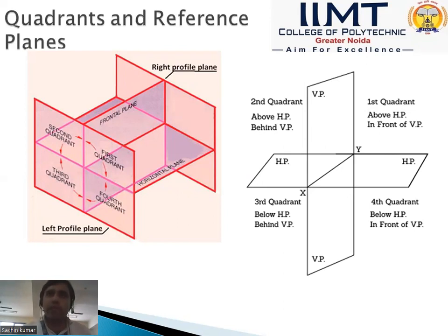In second angle projection and fourth angle projection, the front view and top view of the object overlap, so we cannot use them. But in first angle projection and third angle projection, the front view and top view lie either above or below the xy line, so we use only first angle projection and third angle projection. We discussed these things in the previous slide, but to understand projection of a line, we repeat them again.